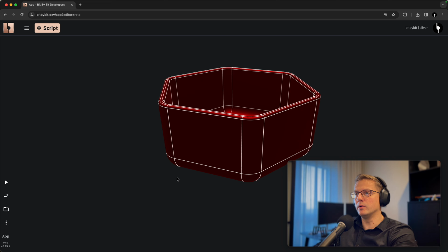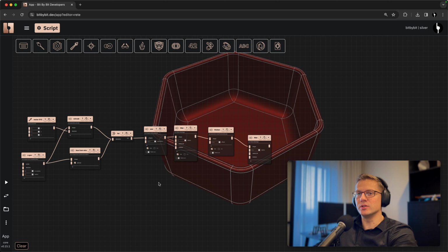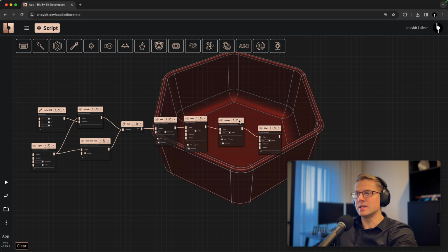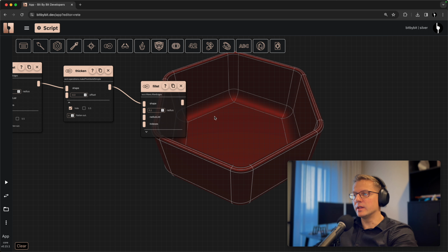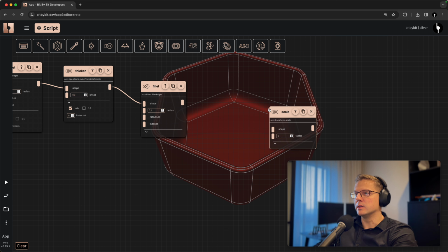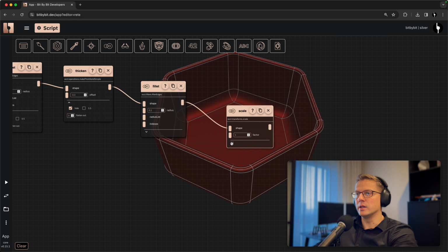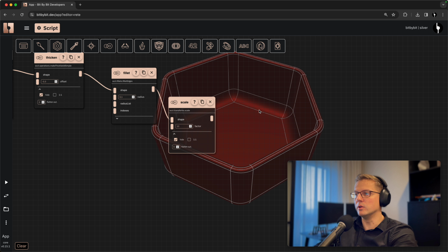It's quite simple, and I don't want to model it further because I just want to show you how you can save this model to an STL file now. And before we do that, I want to scale it just a little bit. So I'll use the OpenCascade scale command like this. I'll hide it because I don't want to show this. I just want to use this scaled version of the model just for an STL file.